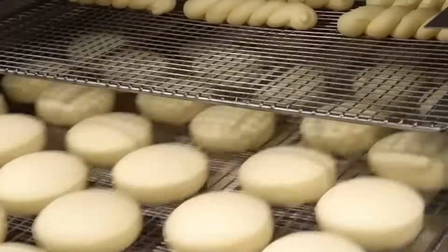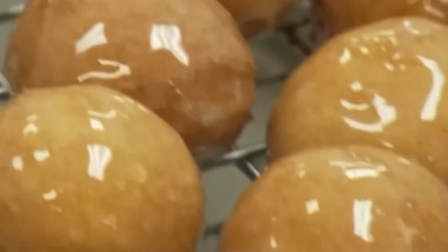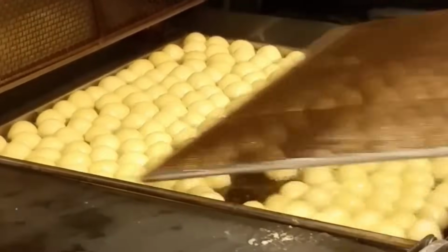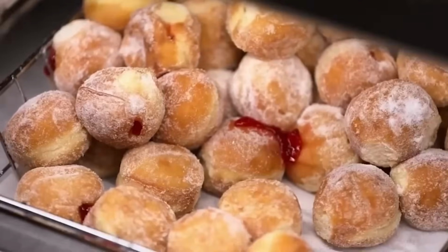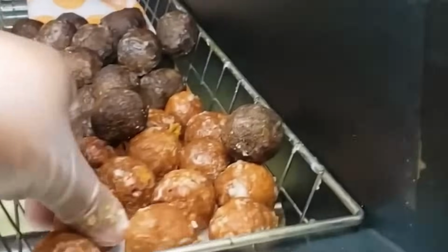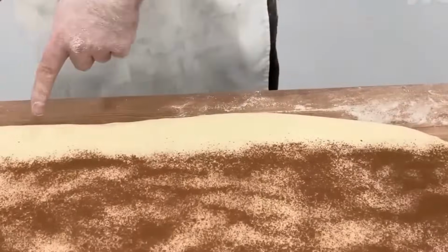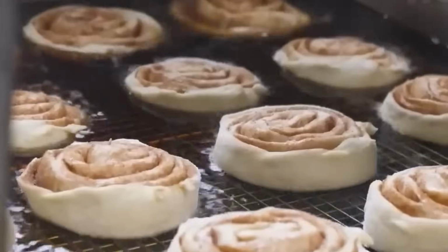Once mixed, the dough is transferred to a resting trough conveyor for gluten relaxation and hydration equilibrium, allowing for consistent sheeting performance. The rested dough moves to a multi-stage sheeting system composed of compression rollers that gradually reduce thickness in incremental stages. Roller gap adjustments are motorized and recipe controlled. Final sheet thickness is typically 9 to 11 mm, depending on the donut style.